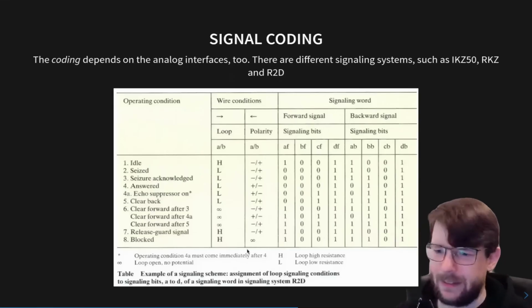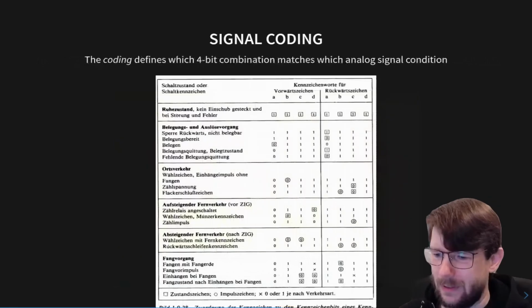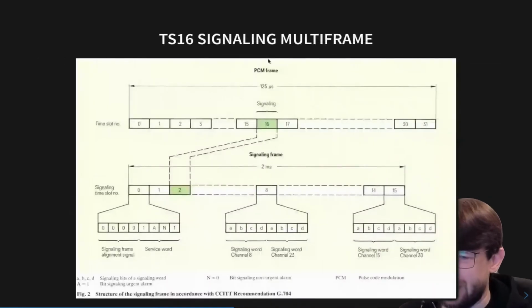So that depends on the specific analog interface and the standard that it applies to, but all of the previous bits up to here are universal for all of these PCM30 equipment types. I think there are some differences in how those A and N bits are used between the equipment called PCM30/32, which is the earliest equipment used by Deutsche Bundespost in Germany, and later equipment which was just called PCM30 without the /32. There were some minor differences here.